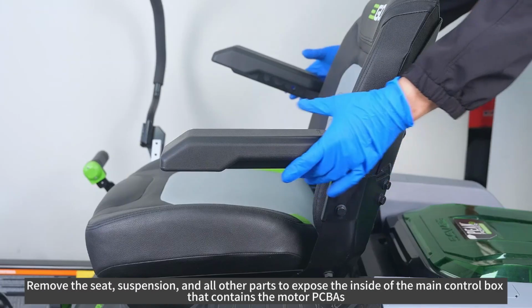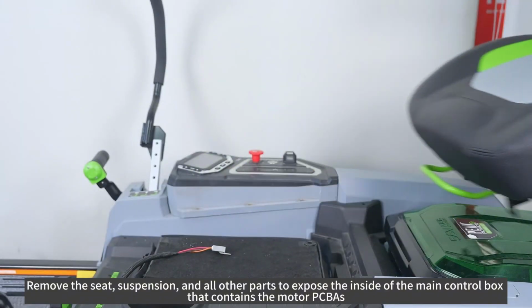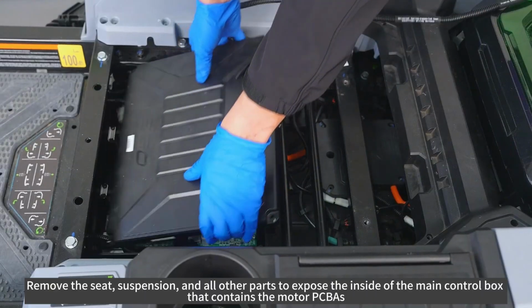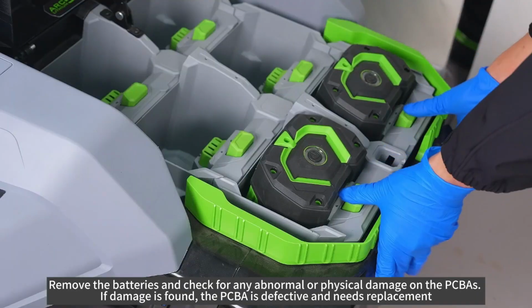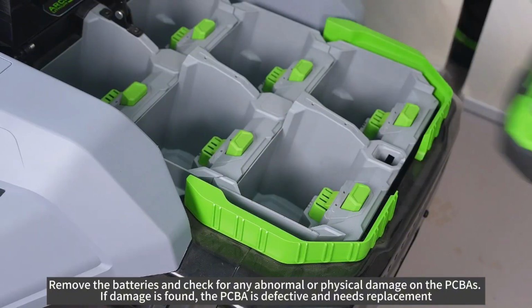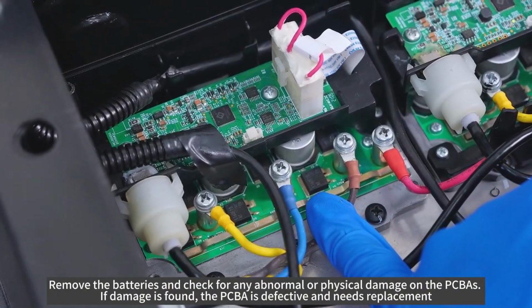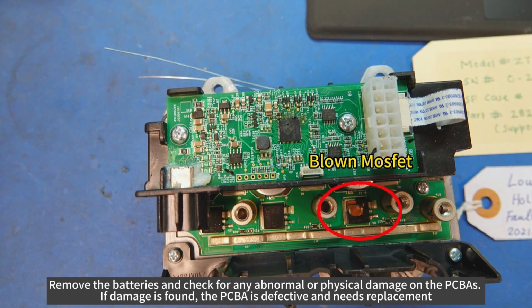needs replacement. Remove the seat, suspension, and all other parts to expose the inside of the main control box that contains the motor PCBAs. Remove the batteries and check for any abnormal or physical damage on the PCBAs. If damage is found, the PCBA is defective and needs replacement.